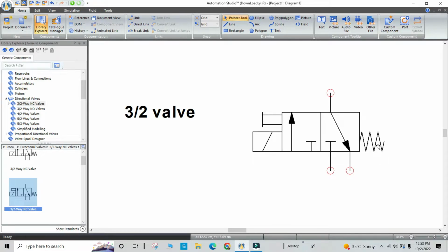But for now, we are going to focus only on push button. So we will just ignore this solenoid because we are not dealing yet with electro-pneumatics, which means electricity is not yet involved in this circuit. So I'm going to put here the actuator. This is an actuator of push button with spring.